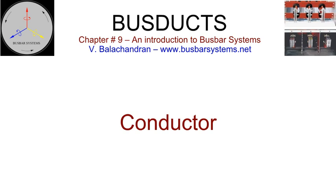For insulated conductors, the site joints need custom-designed seal boots for the configuration and voltage rating. In the absence of insulation, conductors are usually painted or coated matte black or dark shade for better heat dissipation.